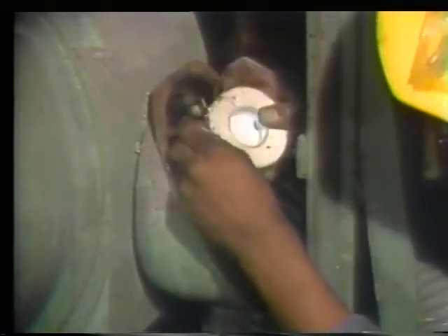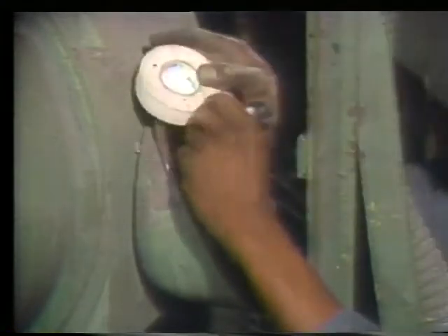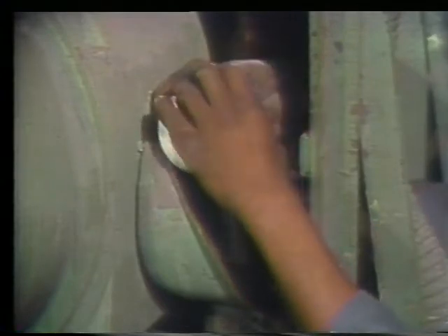Each lead should be marked after it's unbolted. Oftentimes, colored tape is used to mark each lead. Whatever the method your plant uses for marking, make absolutely sure that you mark the leads correctly. If any 2 of the leads are reversed during reassembly, the motor will turn in the wrong direction. Keep in mind that you won't always be the one to put those leads back. Another electrician may be assigned the reassembly task, so the marking must be clear enough for someone else to understand.